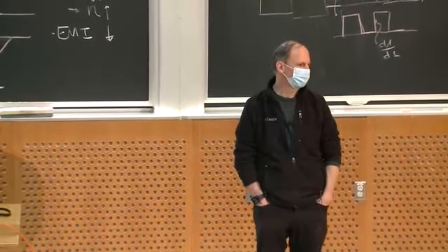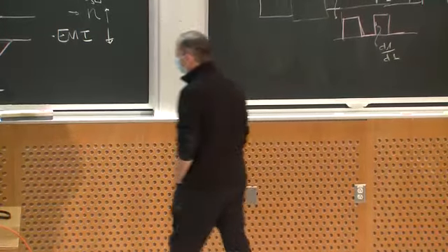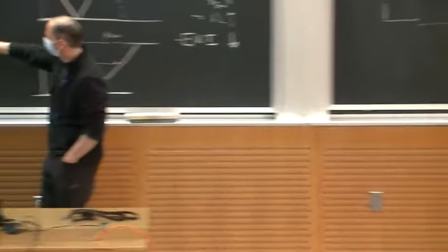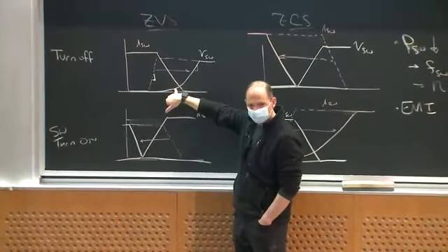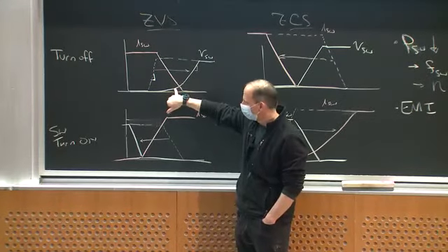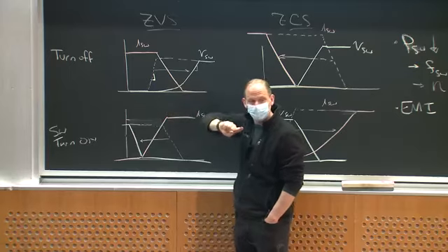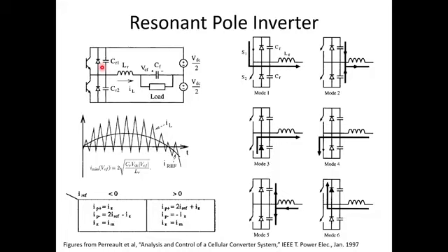It's going to be 0 voltage switching, because when I put a capacitor across my device, I can sort of delay the rise and get 0 voltage turn off. And I'd better turn the switch on when I have 0 voltage, otherwise that energy in this capacitor will be dumped into the switch. So this is going to be a zero voltage switch circuit. This capacitance might be an external capacitor. It might entirely comprise the parasitic capacitance of the device. Just depends on the design, okay?